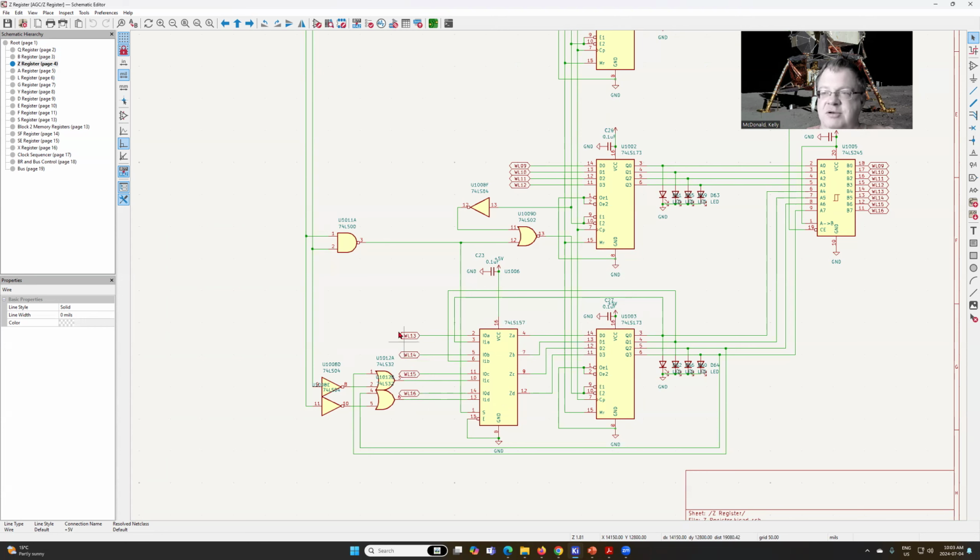So again, we have 2 scenarios. One, if it's normal, if there's no Z15 or Z16 signal, we want to just write in whatever data is on the bus normally. So WL13, 14, 15, and 16. And so basically what I've used is this LS157 as a selector to say, well, what do we load into these registers depending on what condition we're in.